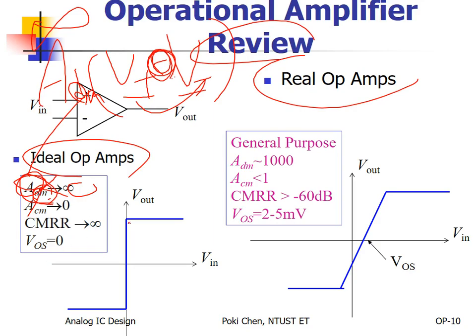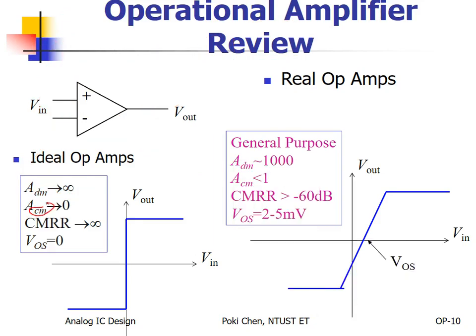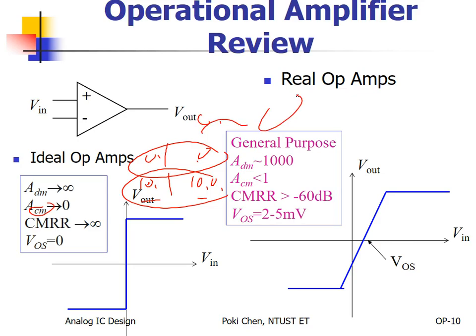But in practical situations, we have common mode. So for example, again, we have positive 0.1, negative 0, or positive 10.1, negative 10. The difference is the same, right? But what is the definition of common mode voltage? The average. Okay, so here the average is around 0, and there the common mode voltage is about 10 volts.